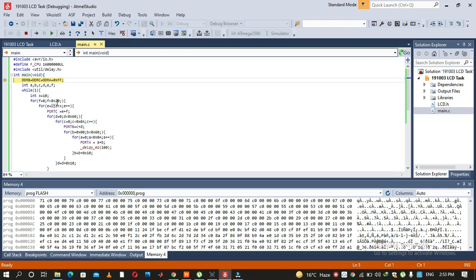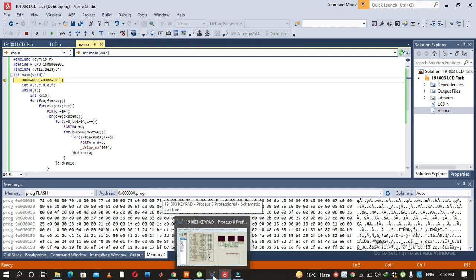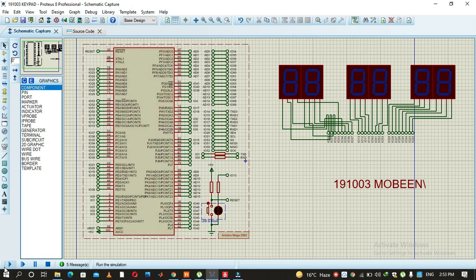When the 12-hour clock is working, you have to use a variable, which in my case is x, and that x is basically what limits my BCD 7 segment display to 24, and not any number that is a multiple of 10. This code working is shown in this Proteus simulation,